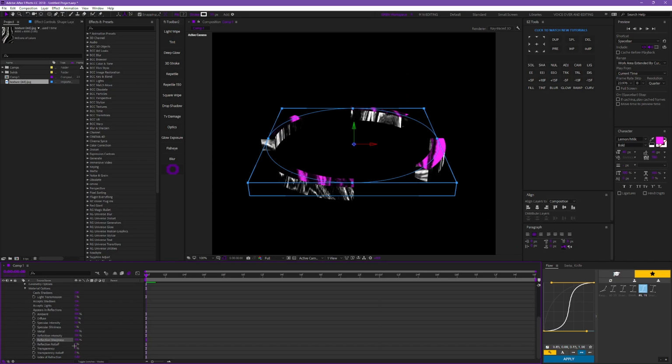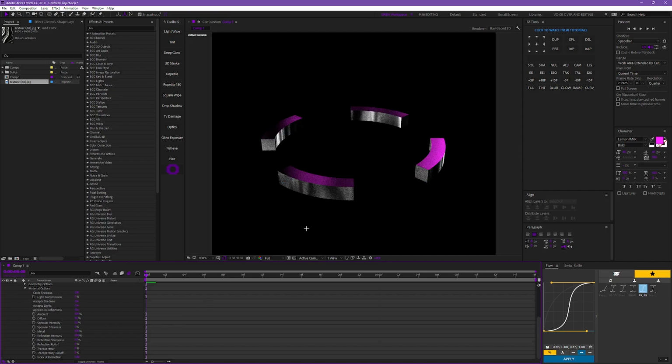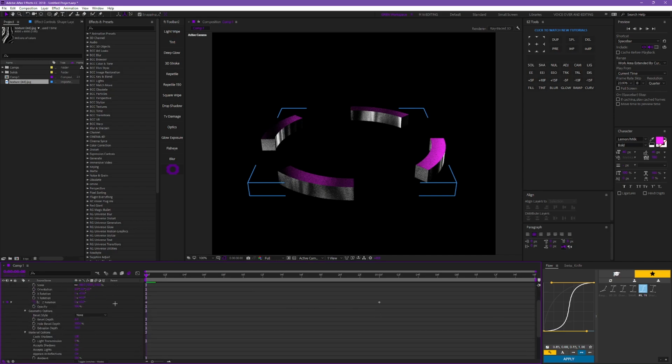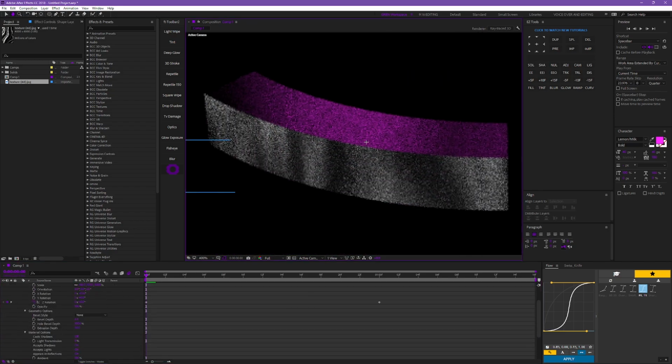And then under the reflection sharpness, I'm going to change that to either 75 or 50%, depending on what look you want. I like to put it to 50% because it makes a really gritty reflection, but you can still tell what's going on. And then underneath the geometry options, I'm going to go back there, and I'm going to show you what the bevel does to this.